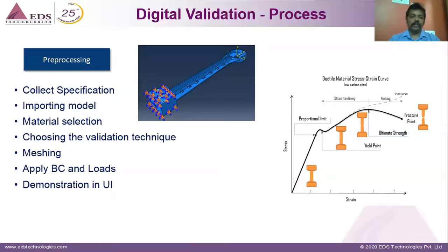Okay, so there are multiple criteria. One criterion which engineers generally follow in industry is that if you have a thickness, then you see that you have a minimum of 3 layers of meshing. If you have a hole, then see how accurately the hole is mapped by the mesh. If you don't consider these kinds of factors, then of course we end up with multiple results, and we will not be able to validate. So this comes by experience.